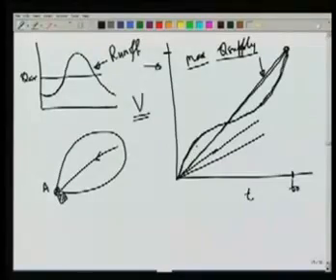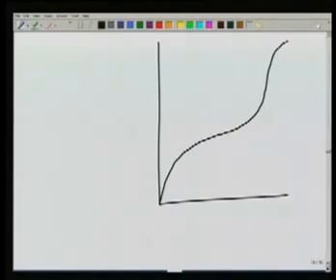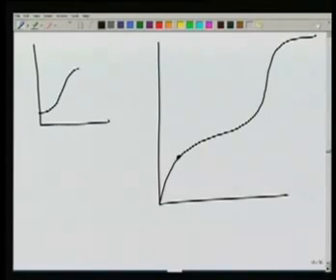So from this figure we can see, if we draw the mass curve again like this, the idea is that during period of low flows we will take water from the storage, and during period of high flows we will divert the additional water from the stream to the storage.